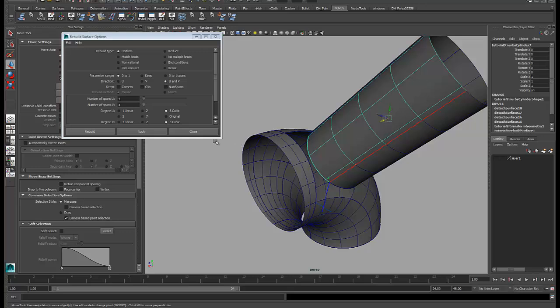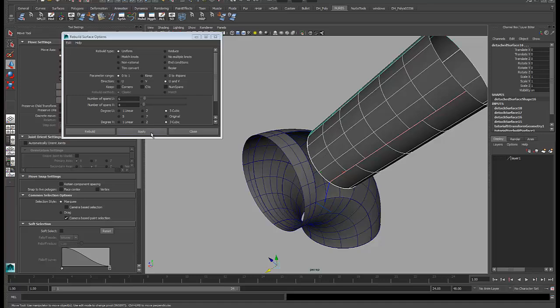squares. So let's just do it this way. I'll rebuild this as a 4 by 4, and you can see that I have elongated rectangles here. It's not the best distribution, so maybe I'll go with a 6 by 4. Okay, so that gives me a little bit better distribution there. So I'll select all of these then and make them all 6 by 4.